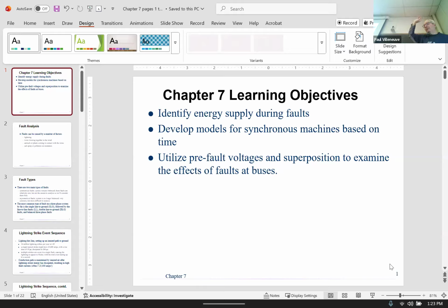So if a fuse that's going down a line to your house burns out, you're going to be out of power for as long as it takes for a crew to get out there. If you're on a breaker or a recloser out on the line and the system is getting restored, they'll try to reclose and get you on. And usually those closest to reclosers will connect very, very quickly.